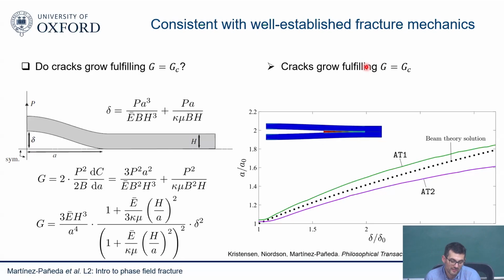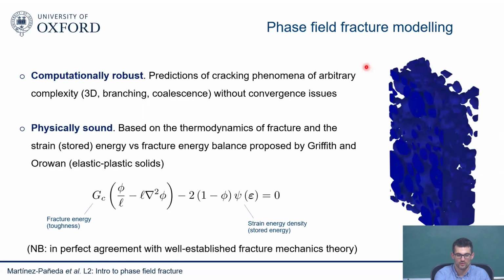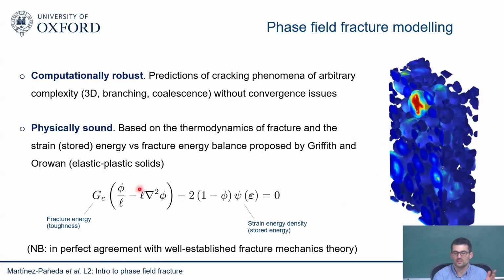So I think the main difference that I find with phase field and other, I would say, non-local continuum damage type of models like those, is that first, you'll see later the value of the length scale, but basically if we look at the equation, it's basically non-local, but other approaches are also non-local, but it's also based on fracture mechanics theory. So everything doesn't rely on some critical quantities that we don't understand, critical damage parameters that we don't know. Everything is based on the length scale that I'll discuss later, and the toughness. And for the material toughness, we have extensive databases.